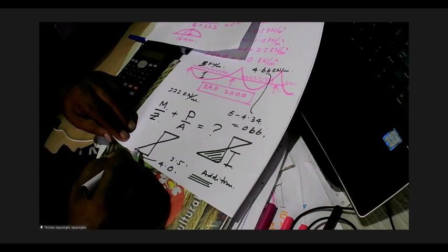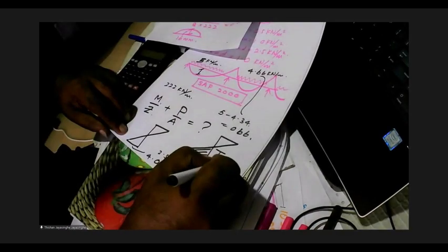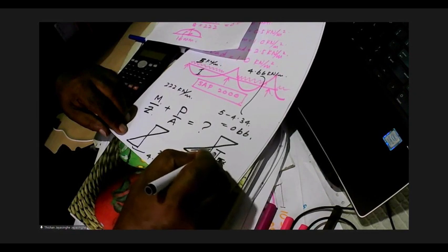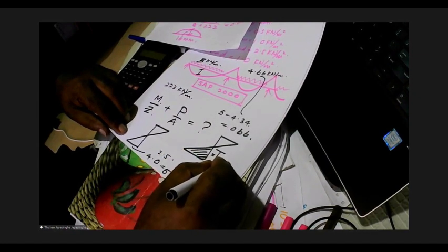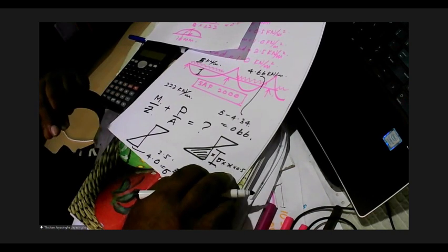And when you know the stress, you can always find the force. Force is given by stress sigma multiplied by half the side x, so you find x multiplied by 0.5 will give the force, and for that force you have to provide reinforcement. So that's what we generally do in pre-stressed concrete flat slabs.